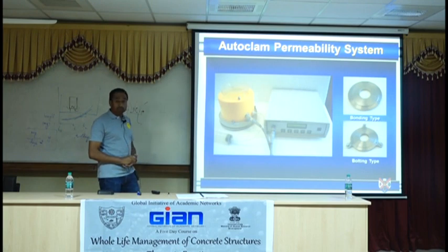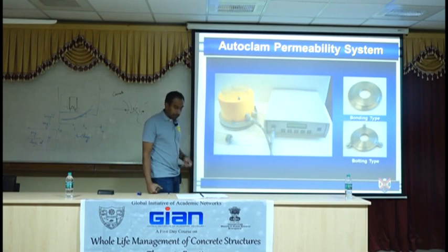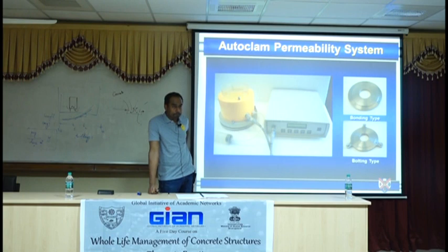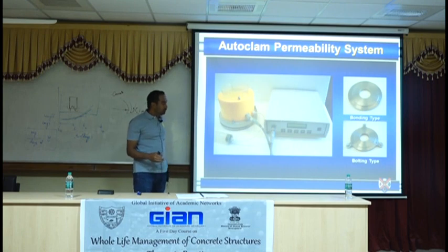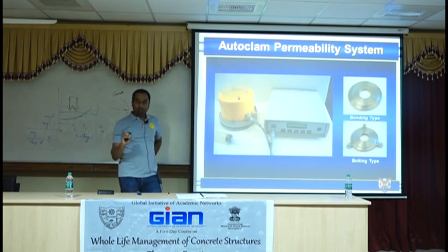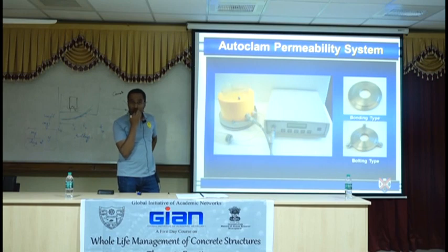Any more questions on that? So which would be the best way to measure the permeability? Because when we measure the gas permeability or the water permeability with the pressure gauge, there is always a possibility that the cells, the gaskets, tend not to be in place. Because of which most of the times we don't get the correct values. I'll come to that in a minute. Any questions? Anyone else?